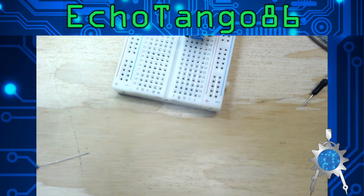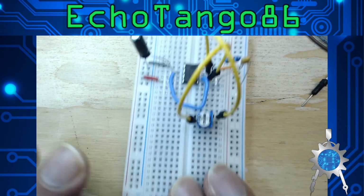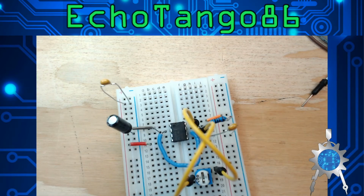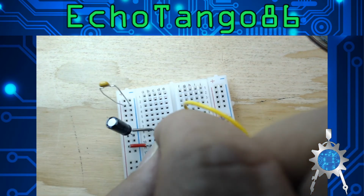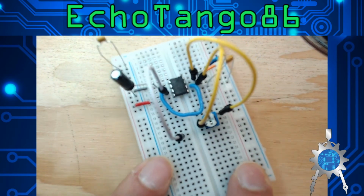Anode and cathode. I always forget which one's which, but yeah. So we're going to do the longer pin, the positive side, and connect that up to pin 3, our output. So where we have that wire for pin 3, we'll plug that in, and then we'll just bring it down here. Plug it in like right there.